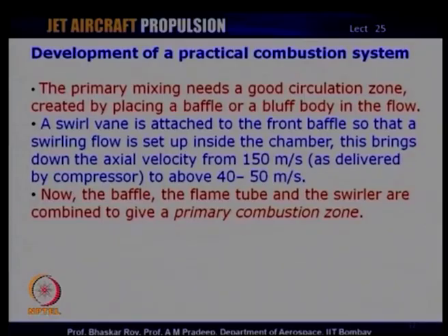And the baffle and the flame tube and the swirler are combined to give the primary combustion zone or the primary zone, inside which the combustion is securely held and continued through the entire process of operation of the engine. So, this is absolutely important to ensure that combustion is continuous, complete and efficient during the entire process of operation of the engine.